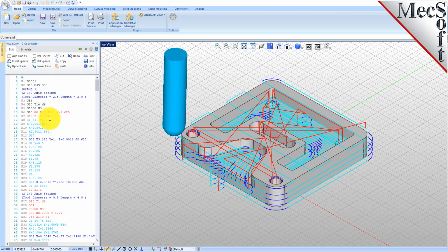Okay, so we made some quick edits. What we can do here is save it right from the Edit tab. Just pick the Save button, and it warns you that the G-code file already exists and asks if you want to replace it. We'll pick OK. Now let's make one additional change to the G-code file, because I want to show you something when we go back to the Project tab. So for now, let's just delete the spaces. Then we'll return to the Project tab by selecting the back arrow right here.